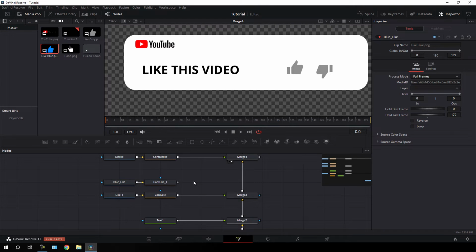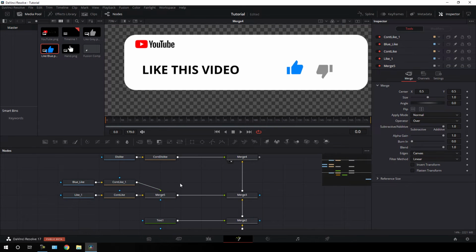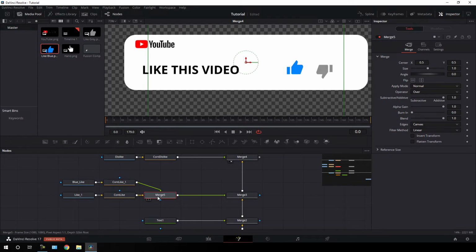And now we have to take one more merge node. So click on this merge button and hold shift on the keyboard and attach this merge just after this controller like. Let's connect this merge just like this. As you can see, connect the green point with this and just drag it right over here. Now we can control the color from here. So this is going to be blend. So hit F2 on the keyboard, call it blend.